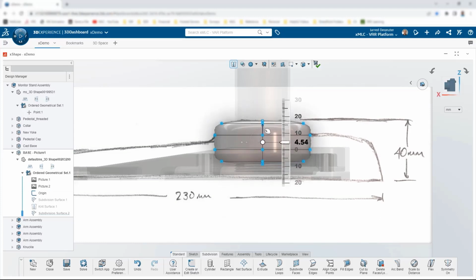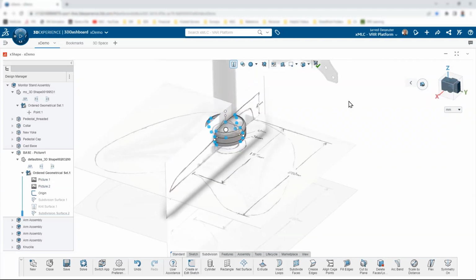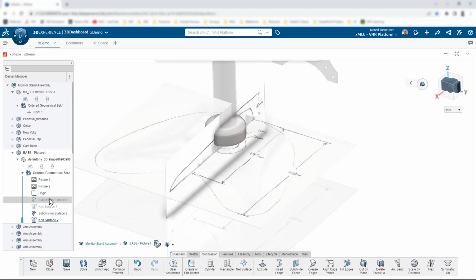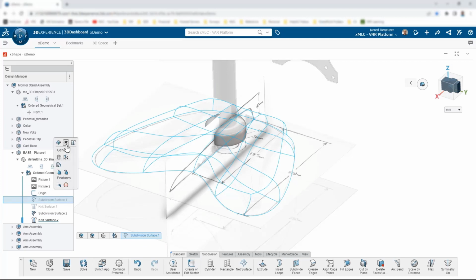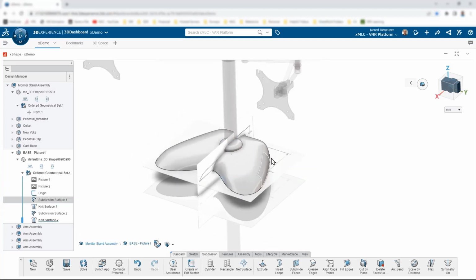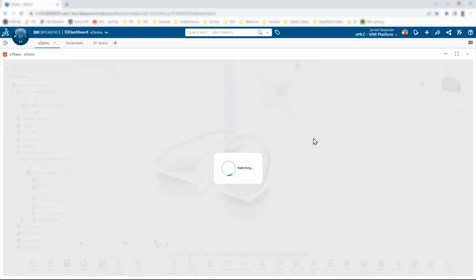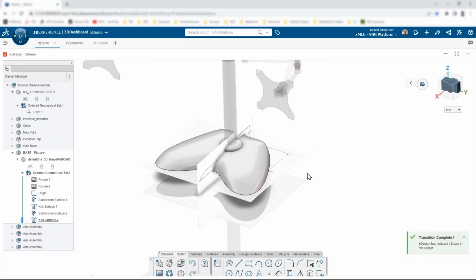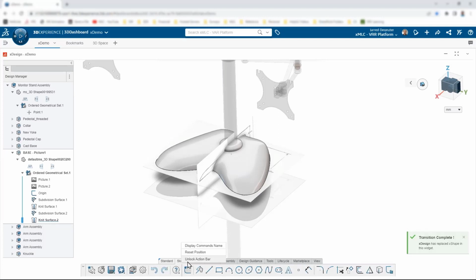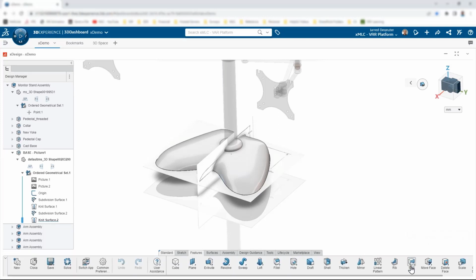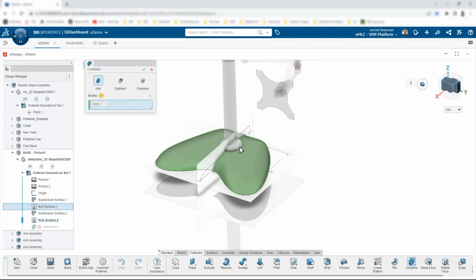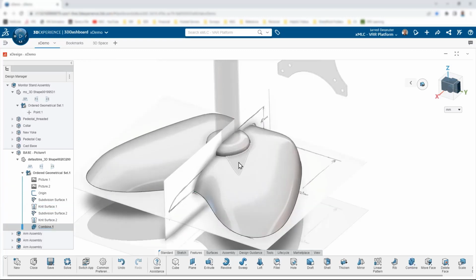I'm going to go ahead and move this up and just position it a little bit more. I think that looks pretty good though. So we'll go ahead and we'll hop out of that subdivision surface that we were working with there. And right now we have two different bodies that have been created. So for those of you who are familiar with multi-body design, you can do that inside of these xApps as well. And what I'm going to do is actually flip back over into xDesign, and we are going to combine those. So we have the ability to do advanced types of features like this. I can pick on those two different bodies and just select them and say, hey, I want to add these to each other. Boom, done.